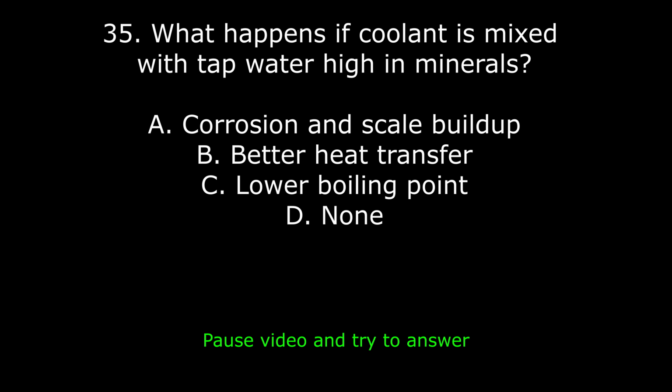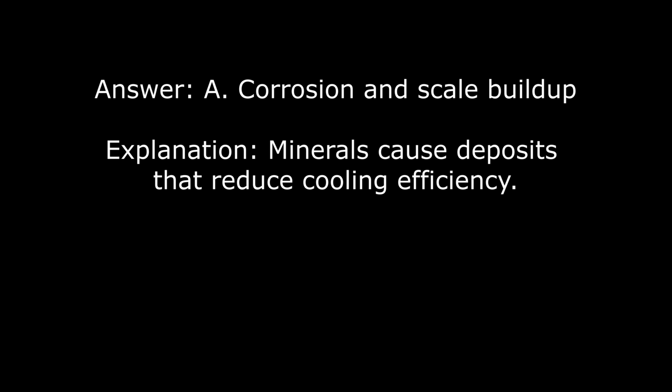35. What happens if coolant is mixed with tap water high in minerals? A. Corrosion and scale buildup. B. Better heat transfer. C. Lower boiling point. D. None. Answer: A. Corrosion and scale buildup. Explanation: minerals cause deposits that reduce cooling efficiency.